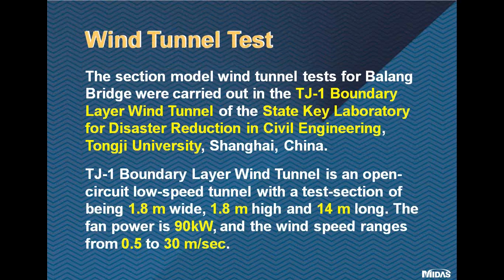Then the section model wind tunnel tests for Balang Bridge were carried out in the TJ1 boundary layer wind tunnel of the State Key Laboratory for Disaster Reduction in Civil Engineering at Tongji University in Shanghai, China. TJ1 boundary layer wind tunnel is an open circuit low speed tunnel with a test section being 1.8 meters wide, 1.8 meters high, and 14 meters long. The fan power is 90 kilowatts and the wind speed ranges from 0.5 to 30 meters per second.